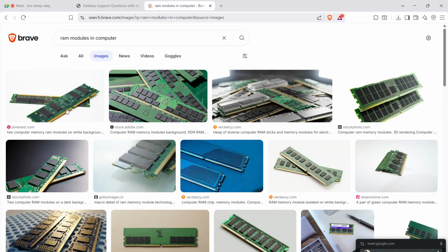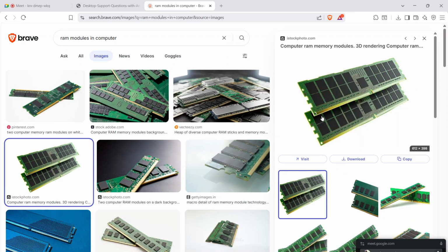What you need to do is remove it and install it again, or press it hard, or rub these lines here, the gold color lines you are seeing. Let me open up this one. See this gold color line. With an eraser you will rub this and then reset it, meaning you will install it again by pressing it.